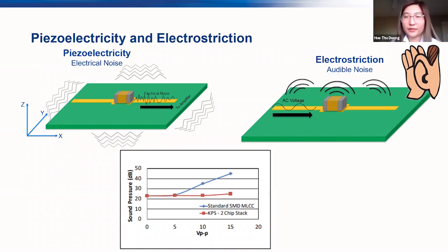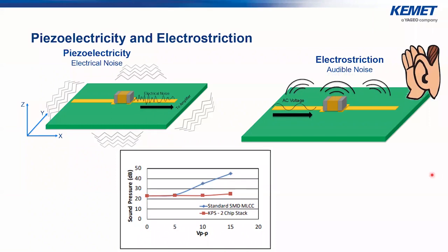For that, would that be something KSIM would be able to simulate, Wilmer? Yeah, our KSIM tool that you can find at ksim.kemet.com on any browser. If you pick your capacitor, enter your operating conditions, and you could switch to see the maximum allowable ripple current, and when you multiply that by ESR, you get your ripple voltage. So yes.